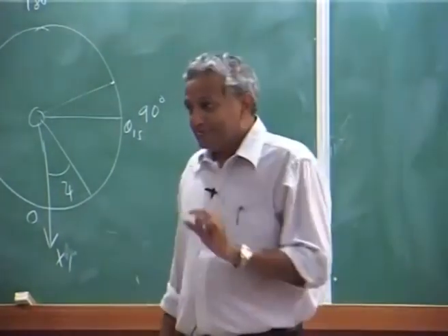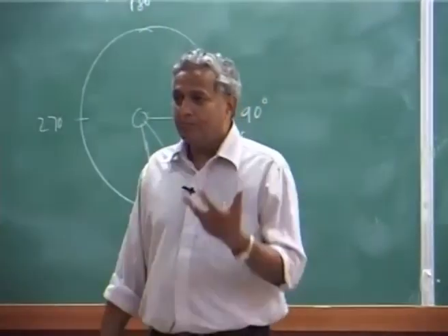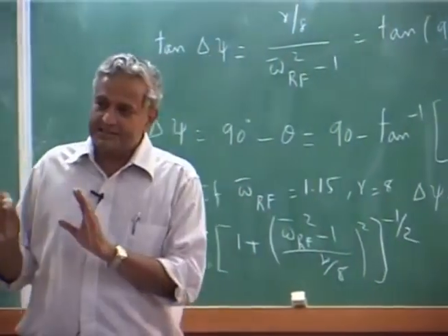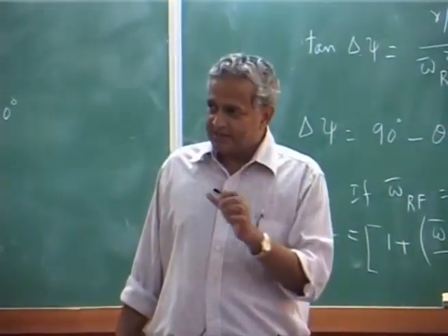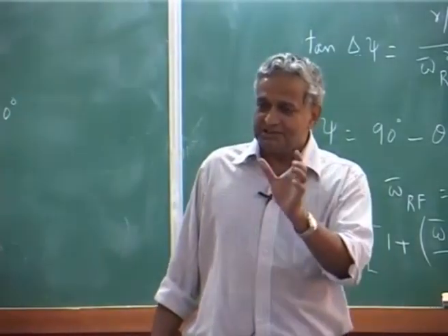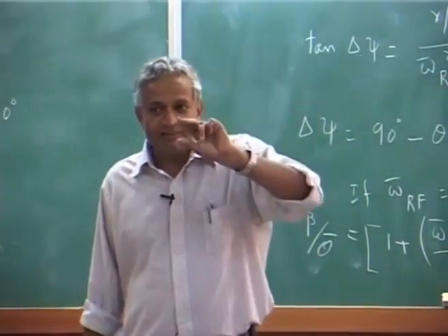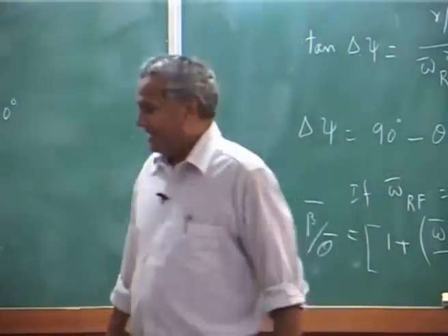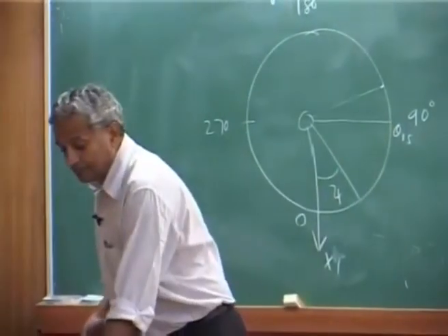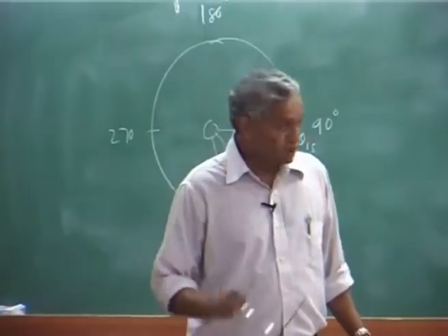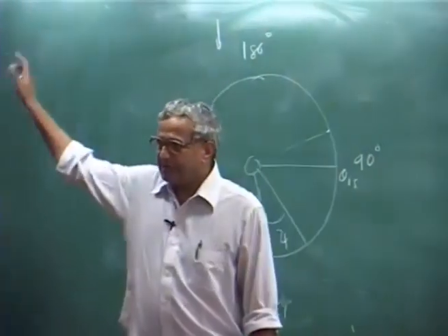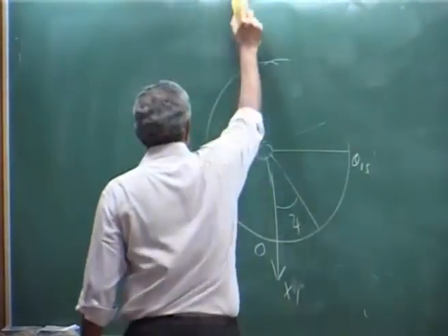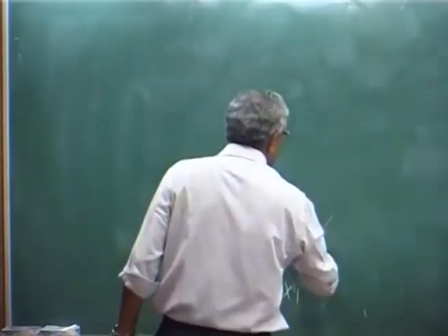But then the problem is, now what we are going to discuss, what happens to the hub moment, okay. Because till now we have studied thrust, side force, longitudinal force and the torque. I said we keep the hub moments for a later thing. Now, let us look at the hub moment which arises due to the flapping aerodynamics. Flapping motion, I would call it flapping motion, because you have to take the inertia also. Now, how do you get the hub moment?